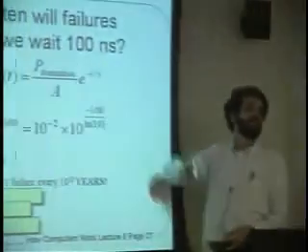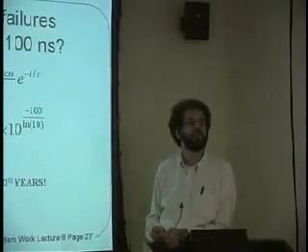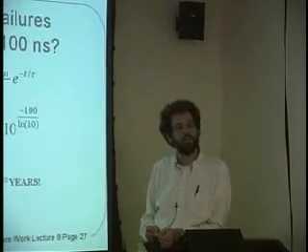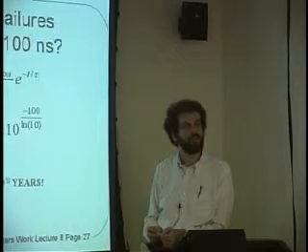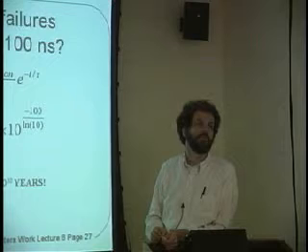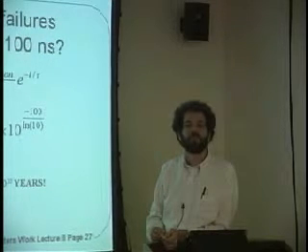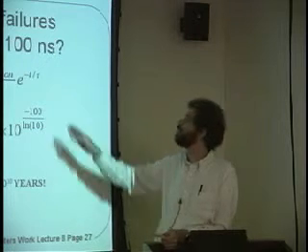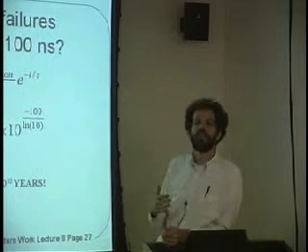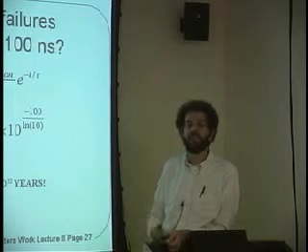And the amount of time you need to wait, if we're going to wait for this long, and this, by the way, is the typical length of time that is used. If you talk to any digital engineer that's out there and you ask them how long do you wait for a metastable state to resolve itself between one state or the other, the answer is 100 billionths of a second. Okay, that's how long we wait. But aiming at 10 to the minus 45th is completely excessive. It's totally crazy. But it turns out that you have to wait 30 nanoseconds at least. So the idea is, well, if we're going to wait for that long, we may as well wait for 100.